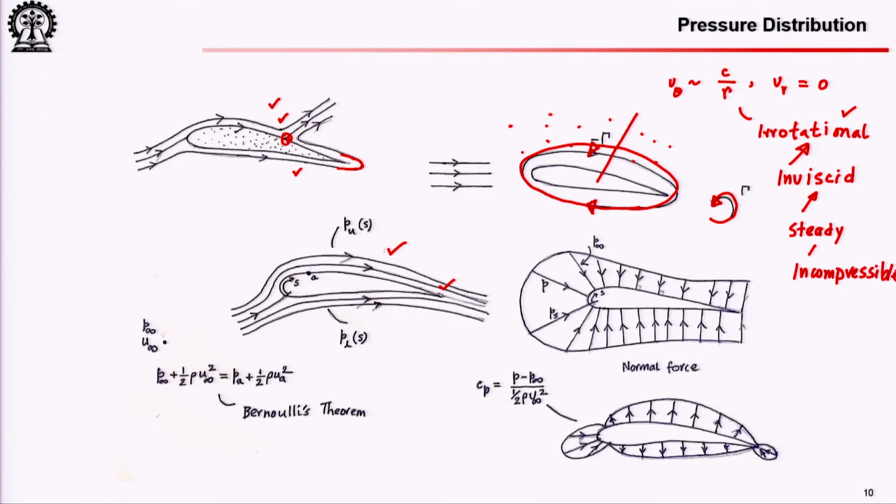So, in those conditions the flow behaves in a compressible manner, but if your flow speeds are low, we will show that below Mach number 0.3 this is what happens, your flow speeds are low. So, it does not matter if you bring it to rest, the change in velocity produces a small change in pressure, which in turn produces a small change in density, which can be ignored. So, then we say below Mach number 0.3 our flow is incompressible.